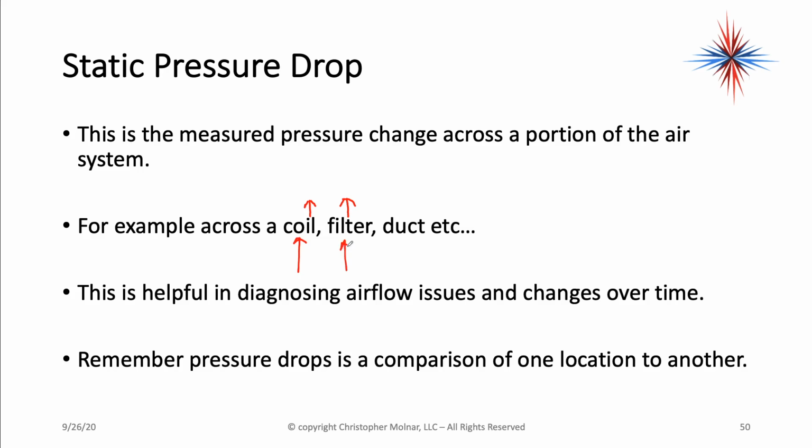In building automation, I can use the static pressure drop of a filter to tell me whether or not those filters are dirty without sending someone on the roof to look at them all the time. Pressure drop will change over time as airflow changes.